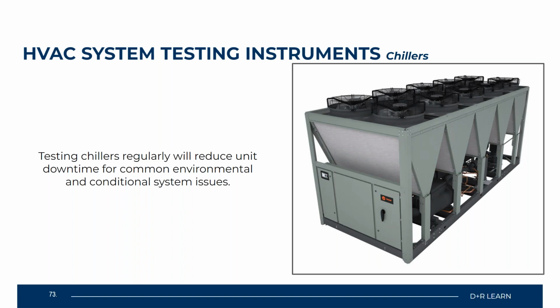So we want to make sure that the refrigerant in our system is charged critically, and we want to make sure that there are no leaks, no signs of oil residue. That is on the refrigerant side of the house. On testing the compressors associated with our chillers, we want to do oil tests, pressure tests, and also electrical integrity tests.